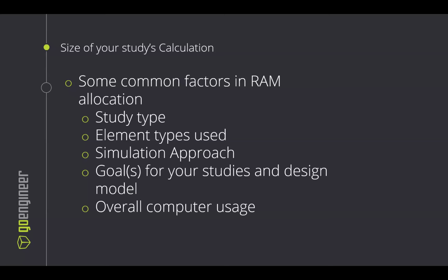It depends on the study type that you're wanting to run. If you're doing a static study, a thermal study or a nonlinear study, a nonlinear study is going to take a lot more resources than a thermal study or a linear study. The elements that you're going to be running and sampling when you apply your calculation nodes for your model to match the model, how those elements, how those calculation nodes group up, can affect how much RAM and resources I need to calculate the simulation. Also, the simulation approach: are you starting small and then growing out? Are you wanting to do the big picture and then zoom in? That's going to be important.